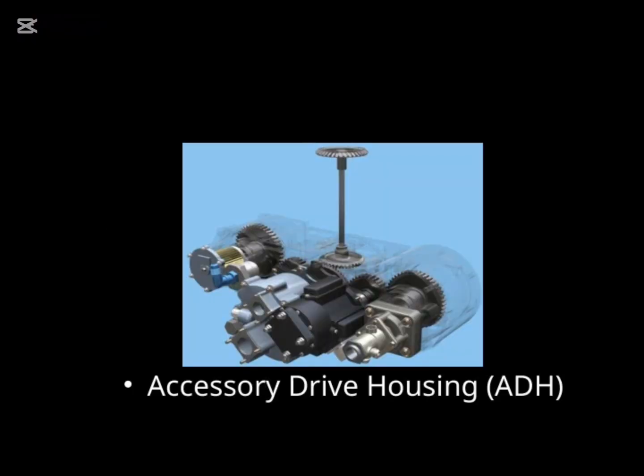Now, let's take a closer look at the accessory drive housing, or ADH for short. This component plays a crucial role in supporting the accessory drive system of the engine. Essentially, it houses the pulleys and belts that drive auxiliary components like the alternator, power steering pump, and air conditioning compressor. By keeping these parts secure and properly aligned, the ADH helps ensure smooth operation and reliability of the entire